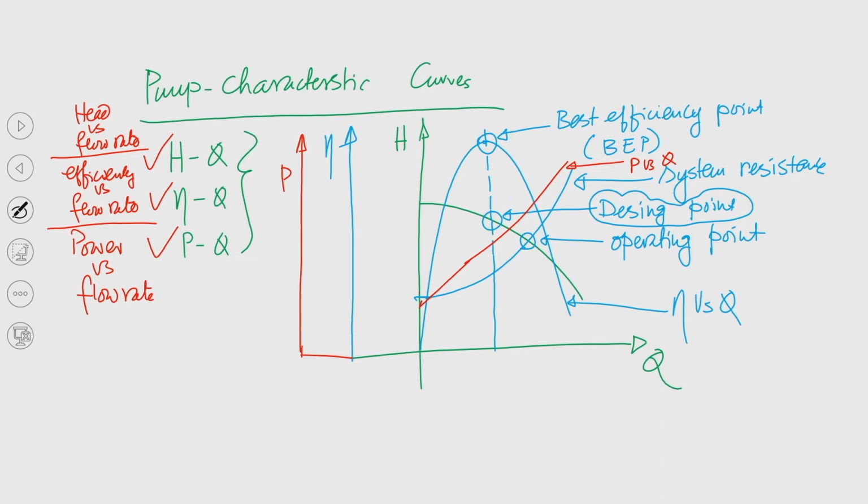Now, this is the static height that we have discussed. So, this is H static. If H static is 0, that means we design the pumping system in such a way that there is no requirement of elevation, the liquid need not be elevated to a certain height. If that is the case, then this curve should pass through the origin, very simple.